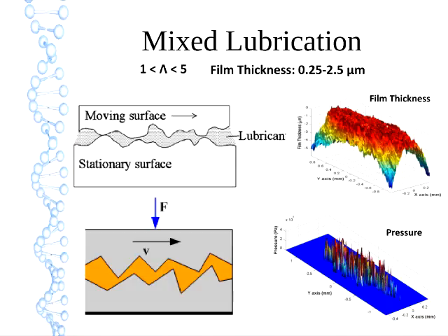When you look at the pressure, with a perfectly smooth surface, the pressure profile will look like a dome, although it may be stretched out based on the aspect ratio of the contact, the relative size of the length and the width of it.